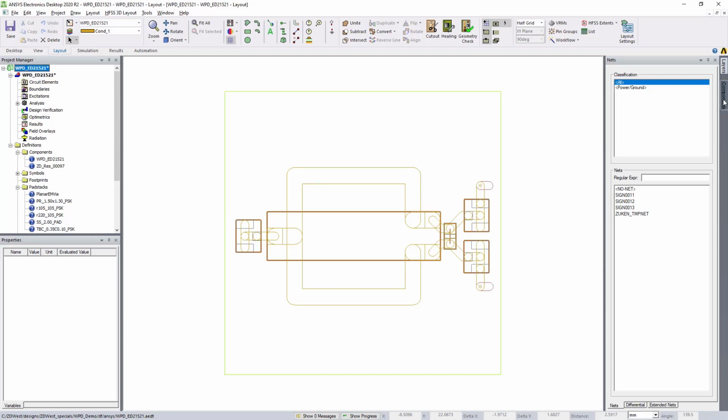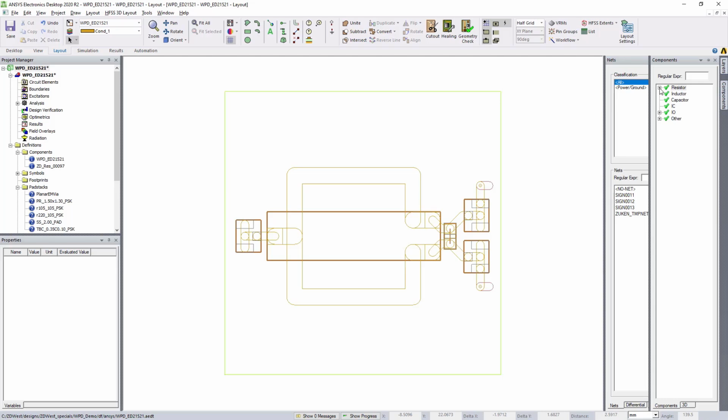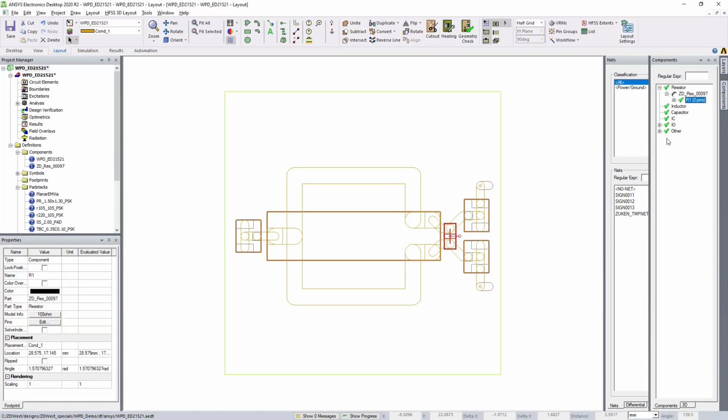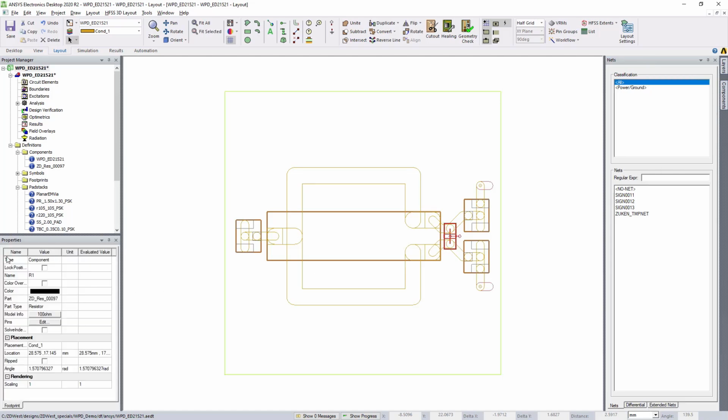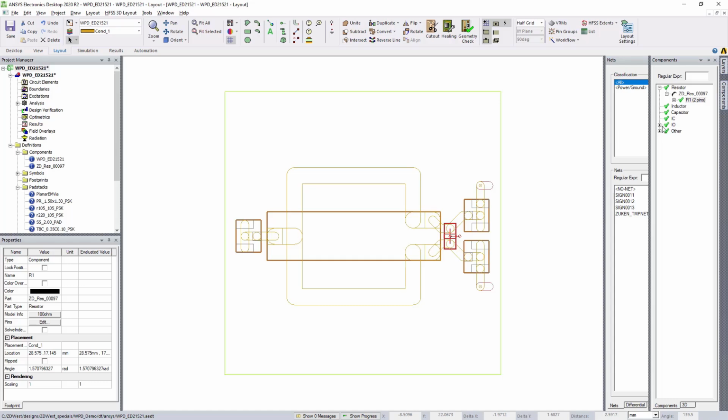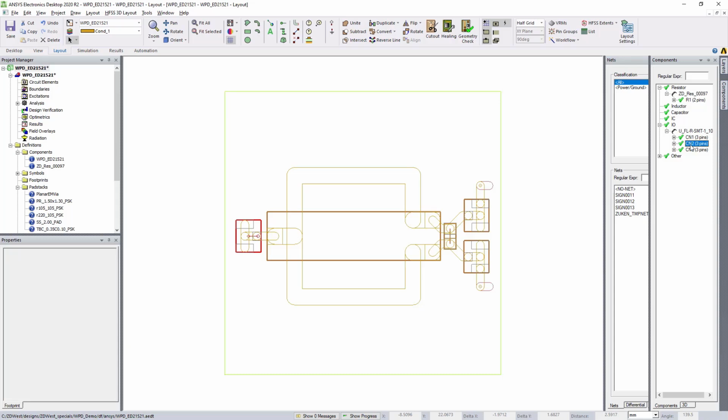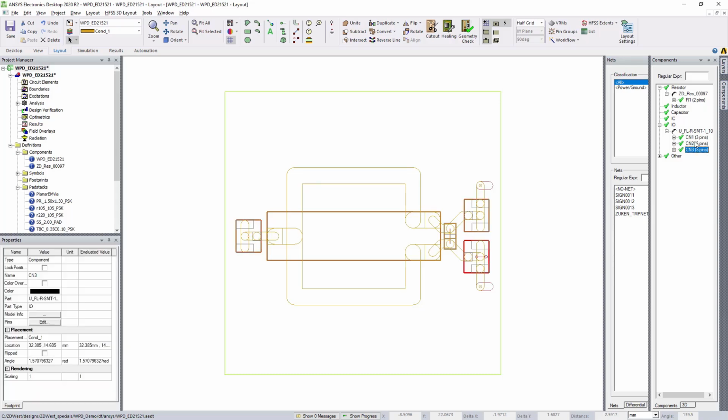We can also look at other elements of the design. So on the right hand side I have the components panel. I can expand to see the components in the design. Here is my resistor and the properties on the resistor, saying it's a 100 ohm resistor to match the 50 ohms on the 2 ports. We can also see the 3 ports in question, so the left hand side single port and then the splitter to the 2 ports 2 and 3.